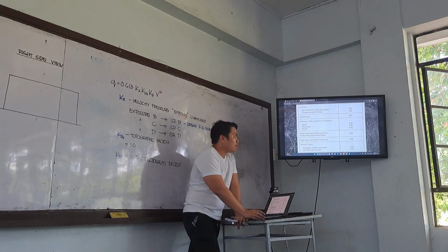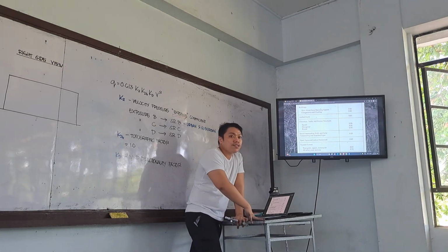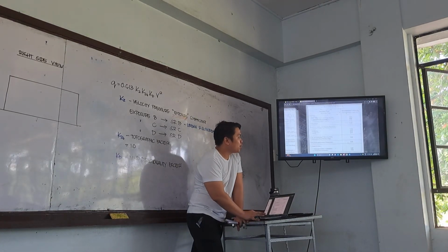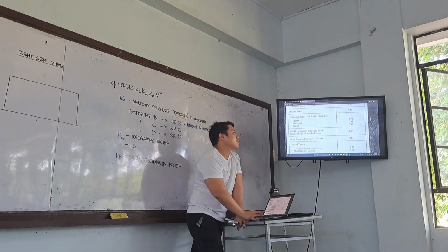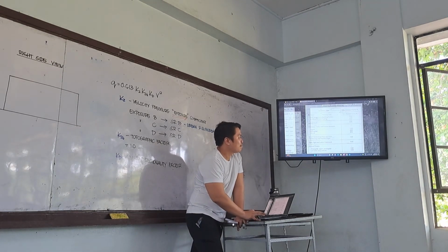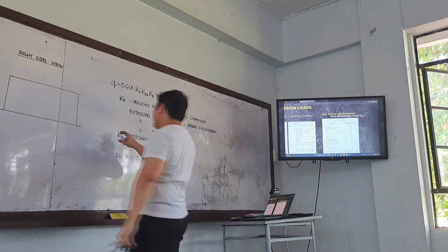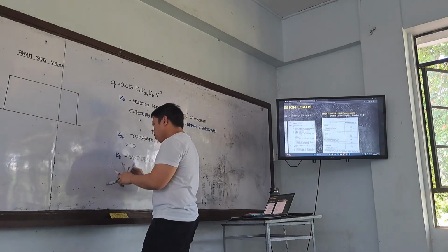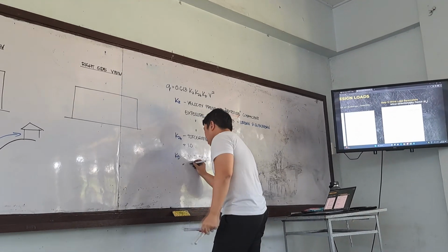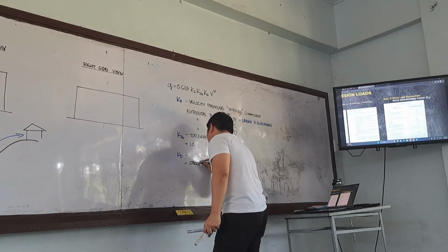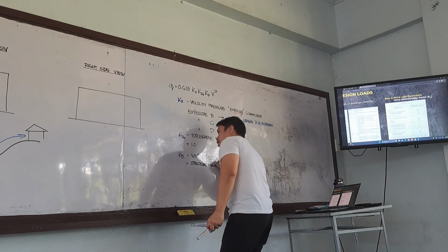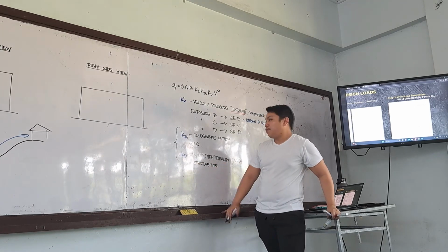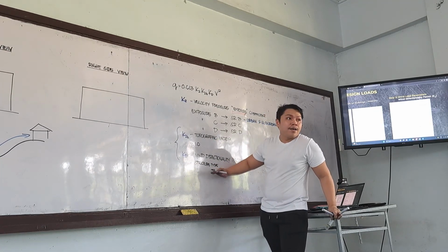We can discuss how to handle the windows in your truss towers, but this is RC design. If you have enough time, I can share how to open windows in trusses later on. So, we are complete: KZT and KD. Your KD is based on the structure type. And take note, your KZT and KD are always fixed. The topography is fixed, and our building is fixed.